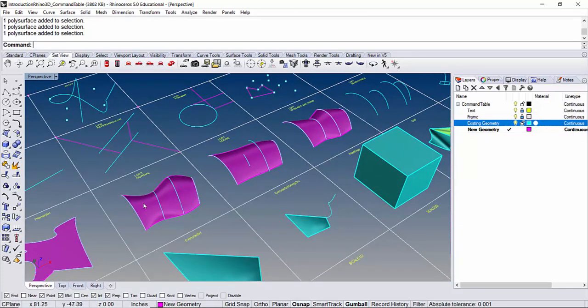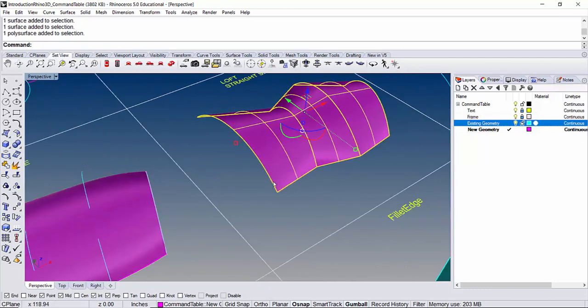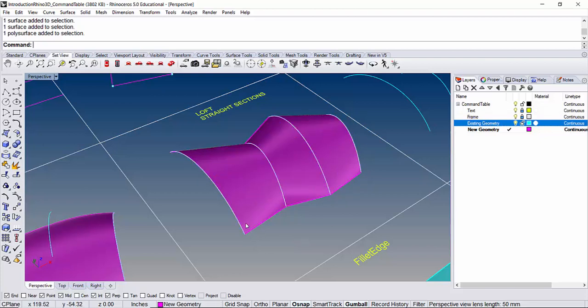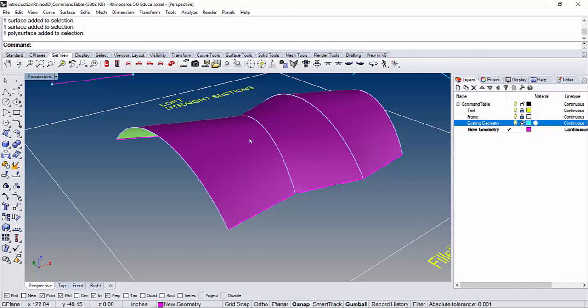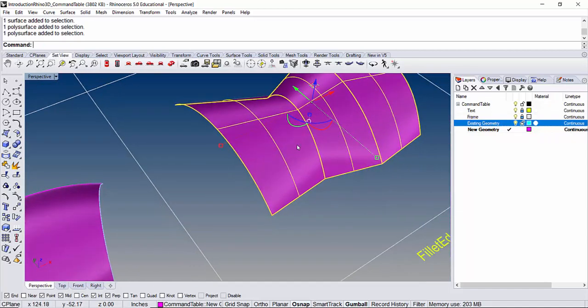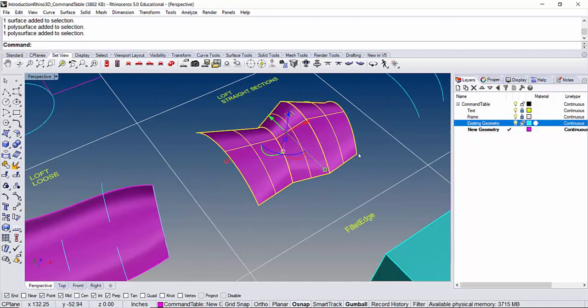So pay attention here. When I'm doing a normal lofting, I have a surface. This one creates a surface. But when I'm creating my straight lofting, it's returning a polysurface, multiple surfaces. What it does is it lofts between two curves and it stops. So it favors your curves more than it favors the surface. Therefore, this becomes ultimately three segments connected together. Does everybody have the straight segments? Yeah. So select these straight segments, and we're going to use a